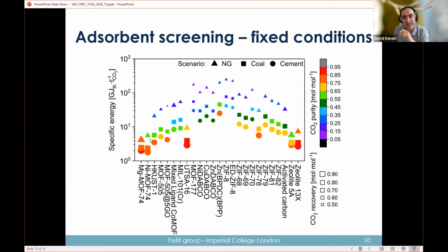we haven't really achieved the claimed benefits of adsorption in this case, because TSA is always suggested as a potential alternative to chemical absorption, because you don't need to heat a large mass of liquid to do your regeneration and thus save energy.